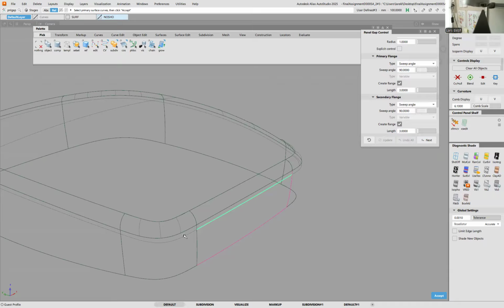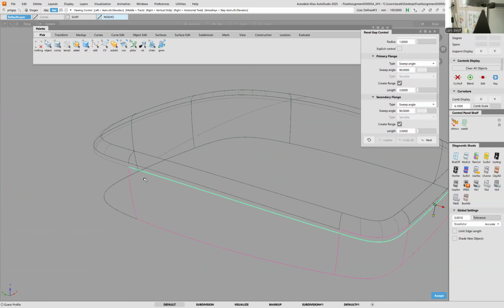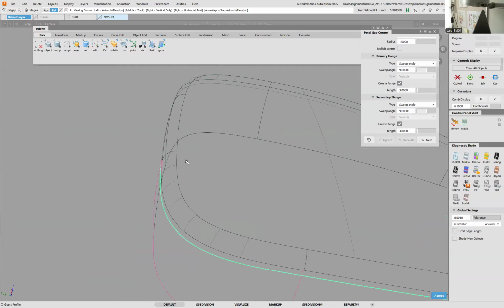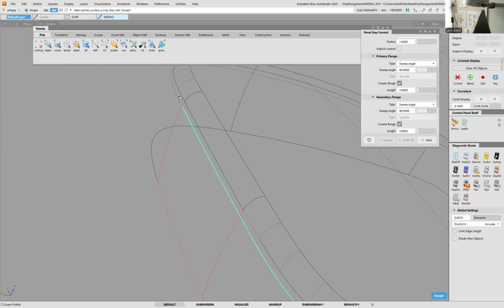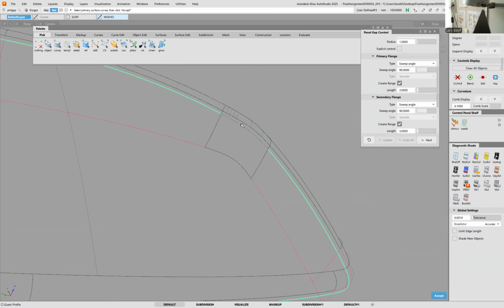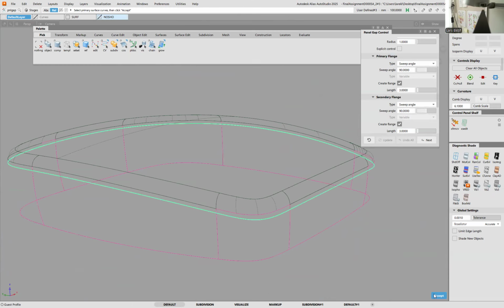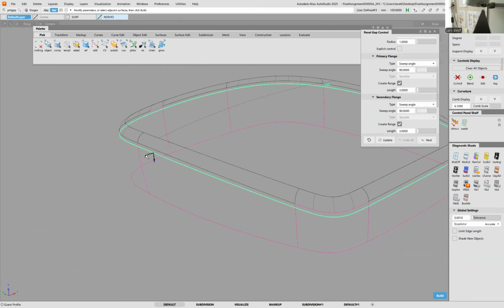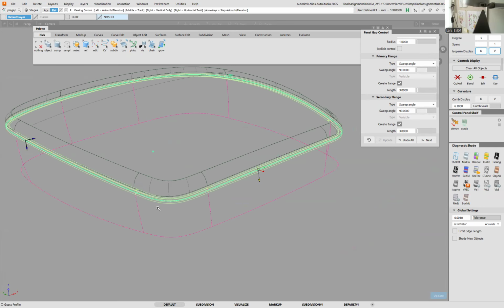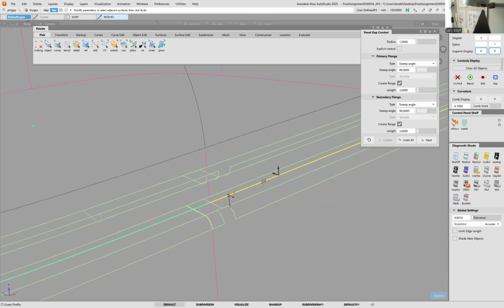So let's continue clicking our way around. Clicking on the kernel surface, which is a curve associated with the mother surface, like so. And if we are happy with that, we click accept and we get 2 arrows, and those should be pointing to the center of the radius as well. So this arrow seems to be wrong. So I click on that one to turn it inwards, and then it creates something here. Let's see what we got, and if it's correct.